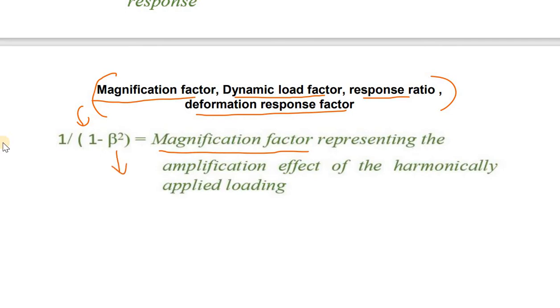And what is beta? Beta is omega dash by omega. What is omega dash? It is the applied loading angular frequency, divided by the free or natural frequency. What is the natural frequency? Root of k by m. The applied frequency will be given in the question.